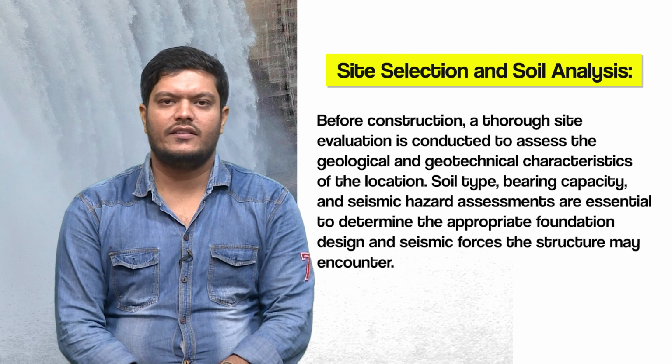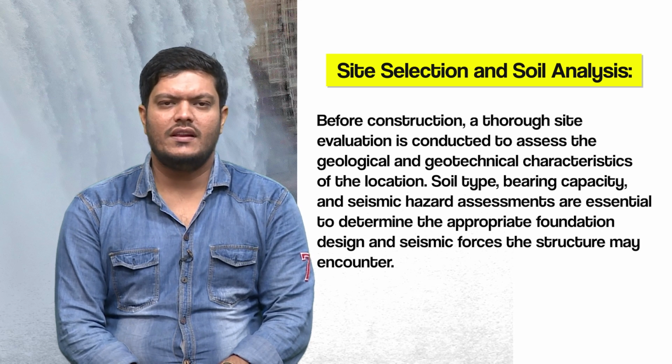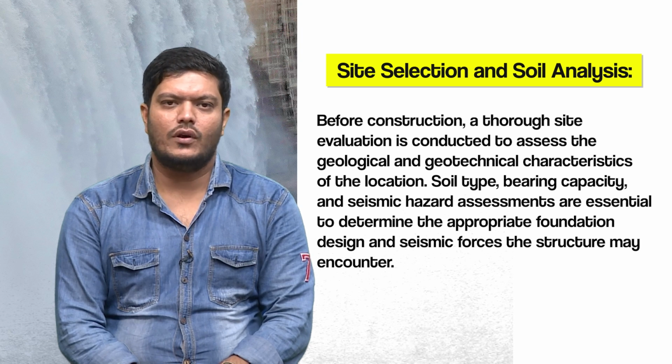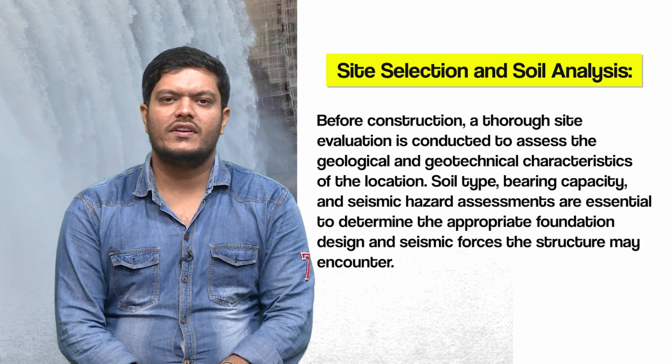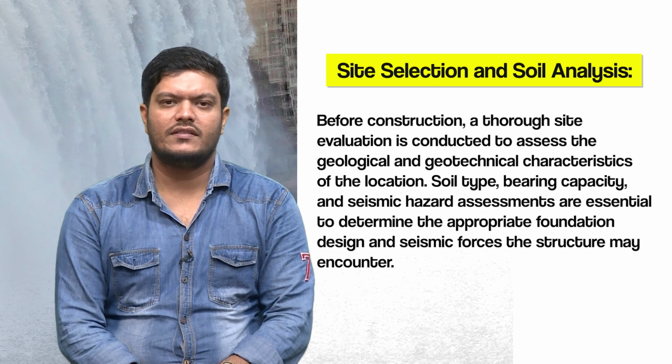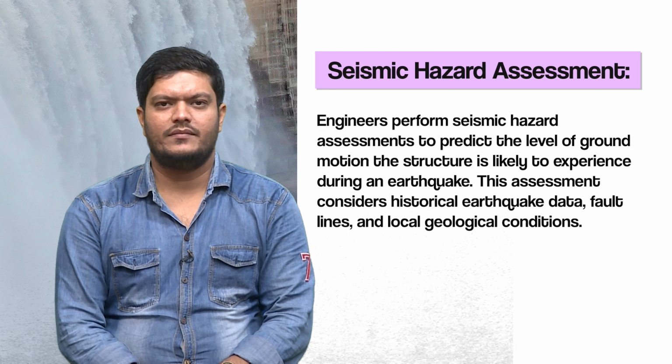Site selection and soil analysis. Before construction, a thorough site evaluation is conducted to assess the geological and geotechnical characteristics of the location. Soil type, bearing capacity and seismic hazard assessment are essential to determine the appropriate foundation design and seismic forces the structure may encounter.